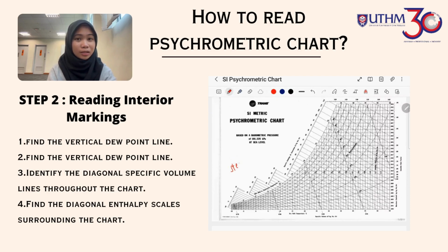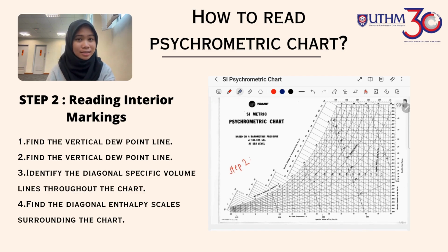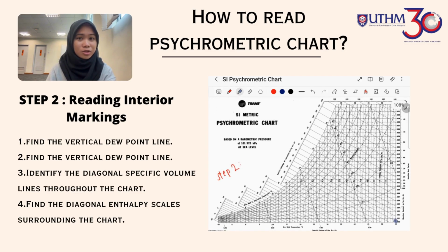Step 2. Reading interior markings. First, find the vertical dew point line just to the right of the y-axis. Find the line with the dew point measurement in degrees Fahrenheit or Celsius.